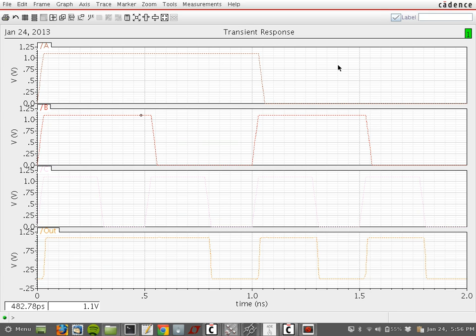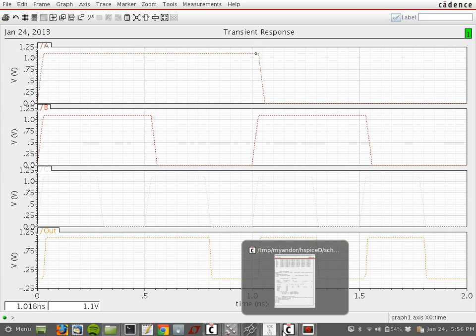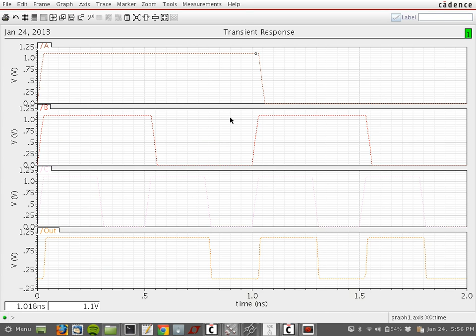There were more things. Yes. Is there any convenient way to assign a value to a bus? To a bus. To an input with multiple bits? Yeah. No, not that I know of. Because here in the stimuli, you can only set it for one signal at a time. No, I don't know of any way. For that, you would need a more advanced simulator, something like a mixed signal simulator or NanoSim or something.